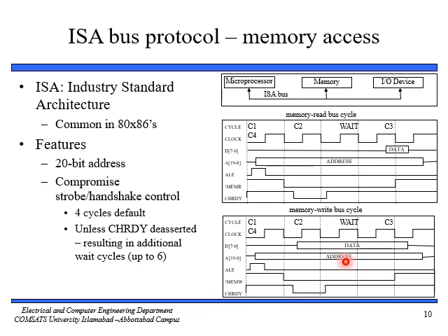And we are using a wait because of this channel ready. Whenever we have channel ready low, we will have to wait. So if there are 2 channel ready low signals, then we have to wait for a longer time. Once the data is written, all the signals are deasserted. So that is typically what is happening in ISA.